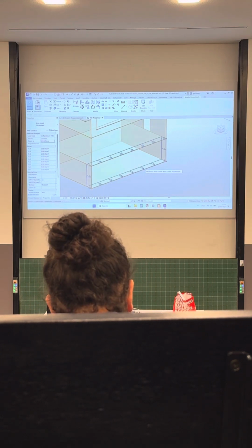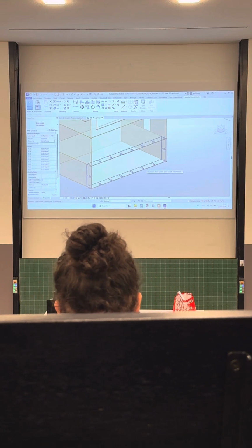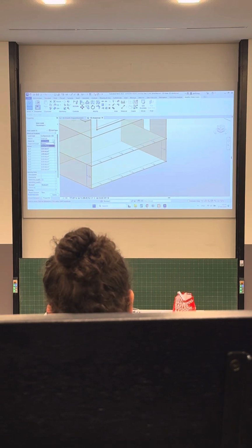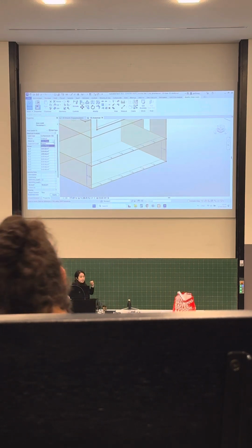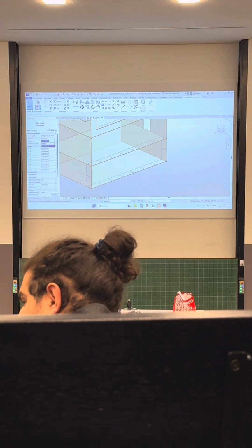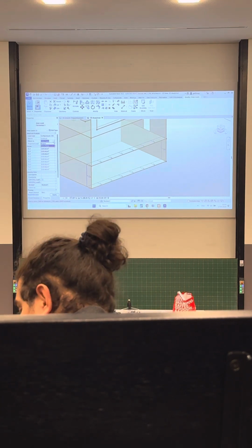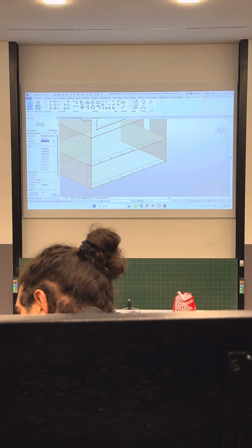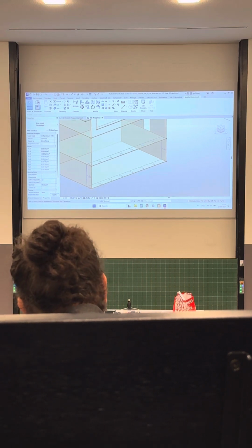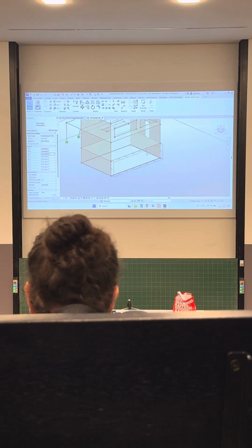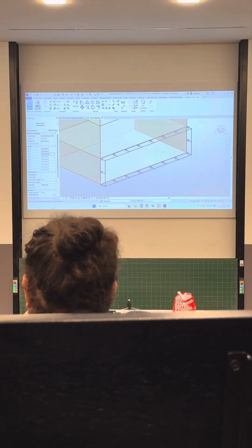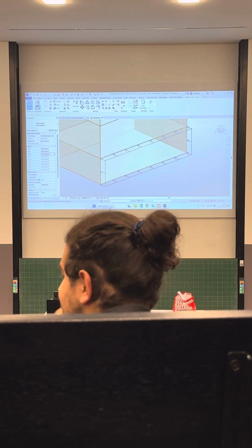For example, here, orient to, in the properties, there is a work plane and project. So check which orientation you're using. Is it project, the global one, or the local work plane? And I want to define an earth pressure, but it's from the inside, so it's illogical. So I put it to minus here. Yeah, so this is the right. But again, as I said to you before, the earth pressure should be variable. 0 on the 0 height.